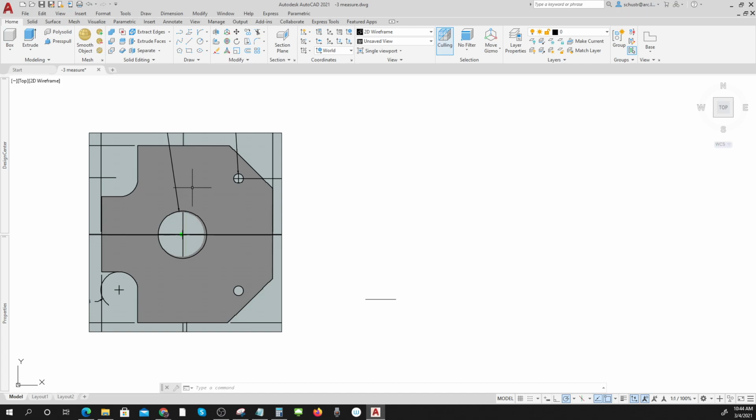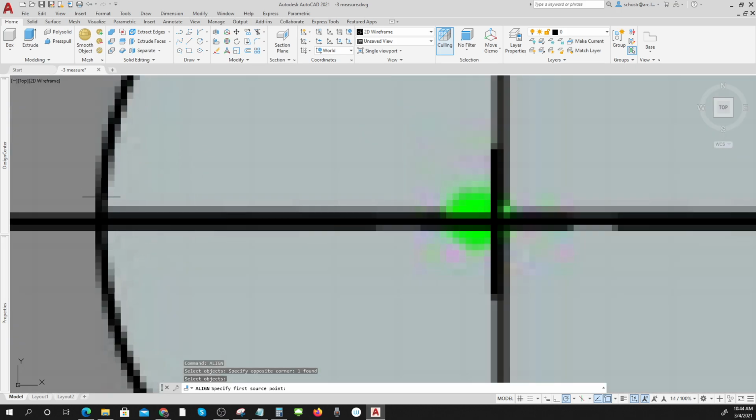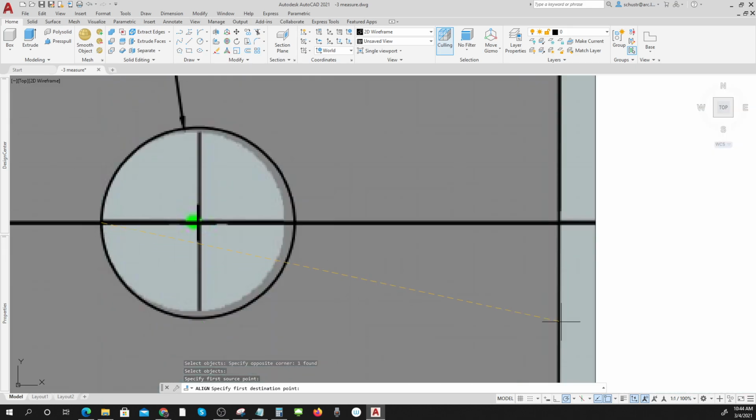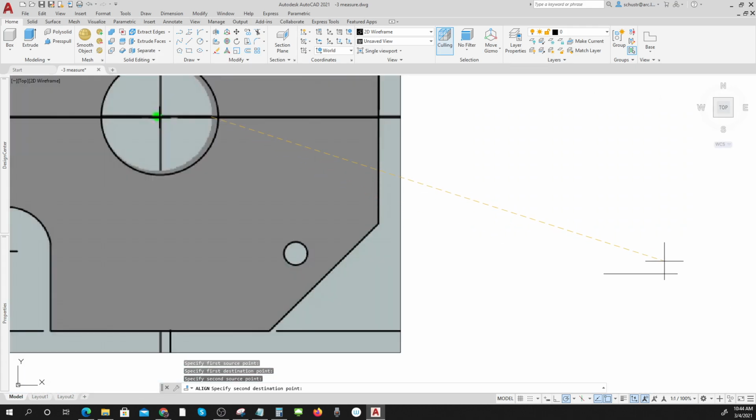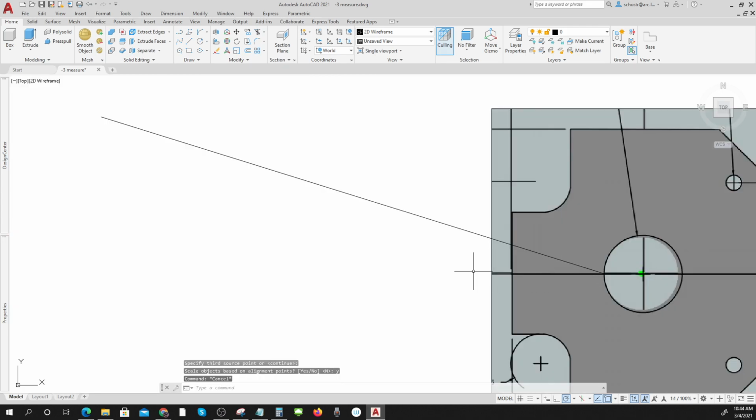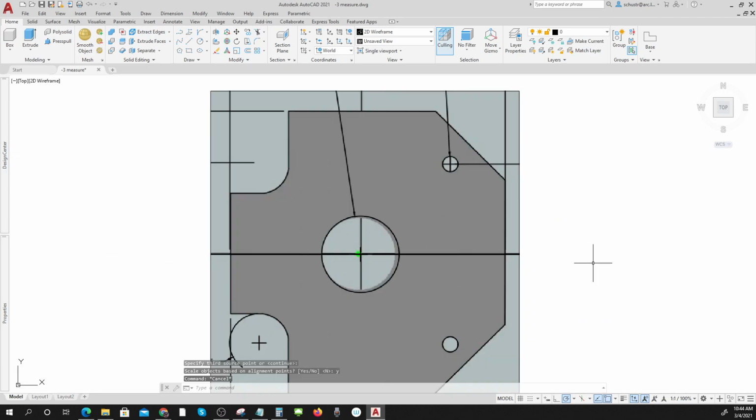So now I'll do my align command. ALIGN. Align my object. Enter. And I'm going to do the best I can. I'm going to pick the middle of the black line as best I can. Put it there. And the middle of, I see some pixelization, so I'll get sort of to the middle of that. There. And yes, so there we go. Now I've got this thing. I think I've got this scale. So now I'm going to try to draw it.